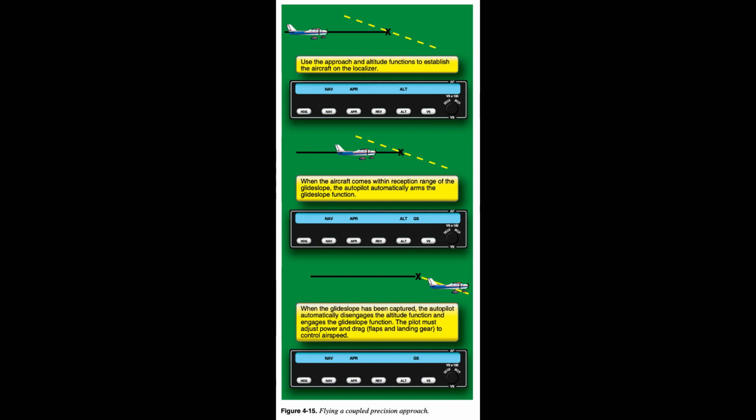Power management. Since most autopilots are not capable of manipulating power settings, you must manage the throttle to control airspeed throughout all phases of the approach. The power changes needed during altitude changes must supply the necessary thrust to overcome the drag. The pilot must coordinate the power plant settings with the commands given to the FD/autopilot. Remember, the FD/autopilot can control the aircraft's pitch attitude only for altitude or airspeed, but not both.